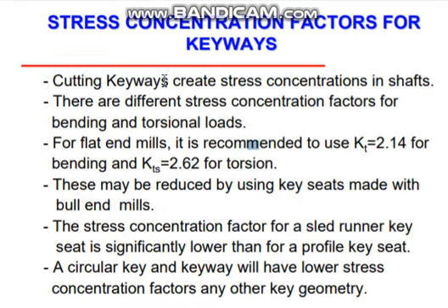And there is stress concentration also, which we have to consider. Cutting keyways creates a stress concentration in the shafts. There are different stress concentration factors for bending and torsional loads. So when we are designing, earlier while designing shafts, we considered KT and KM.